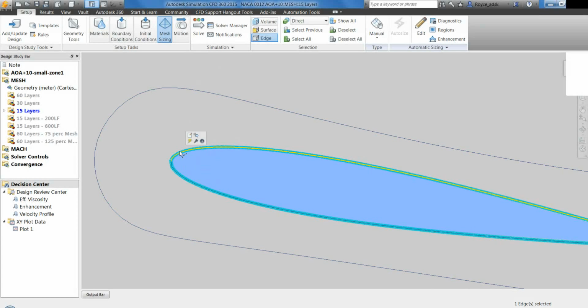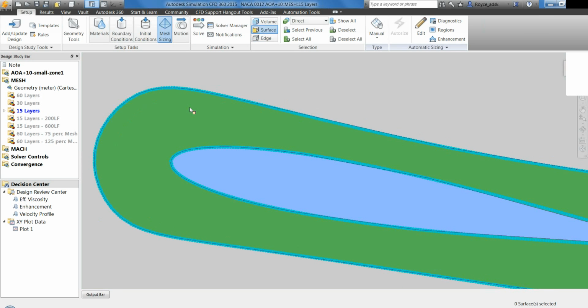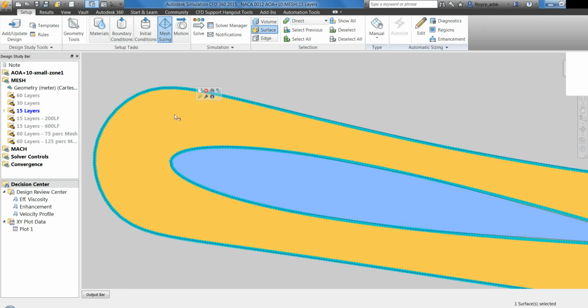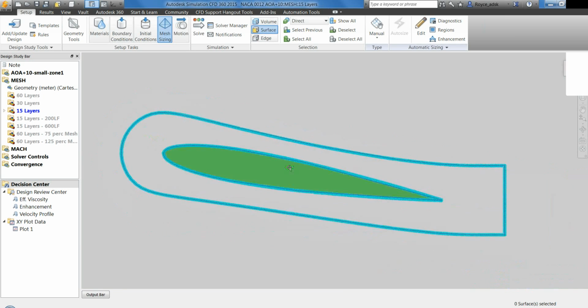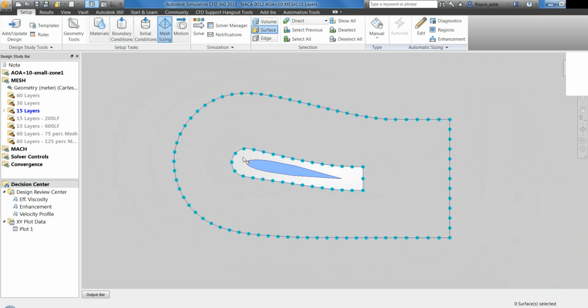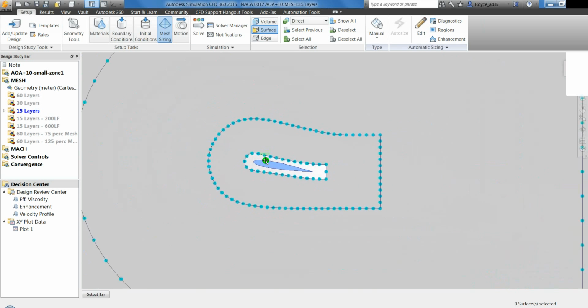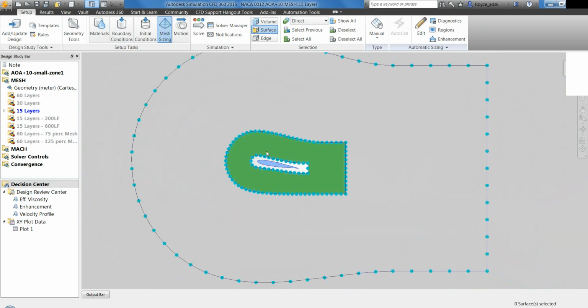So of course we have some nominal value, in this case 2.5 millimeters. And then from here, you'll start defining your surface growth, in this case twice the size, and then growing outwards from there. Okay, and that's what all these different refinement regions are that you can easily define within any CAD package that you like. Okay, going outwards.